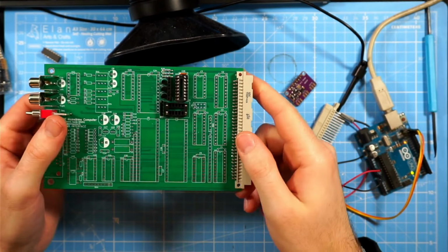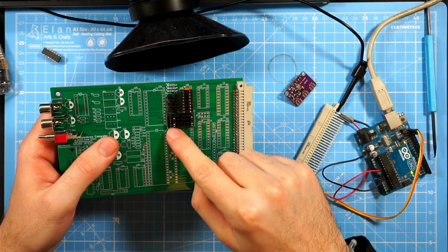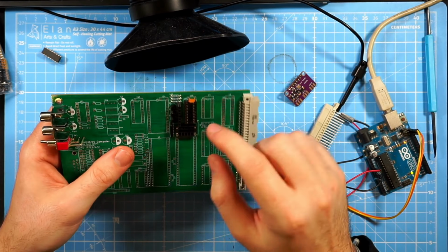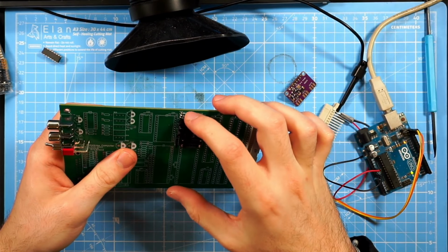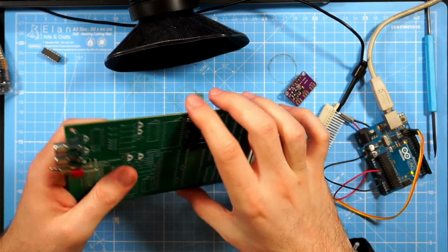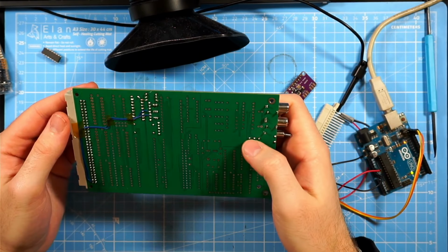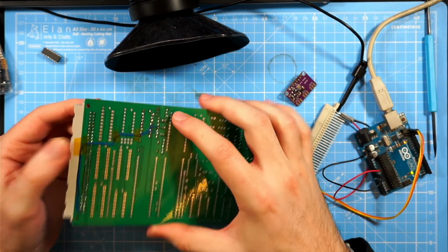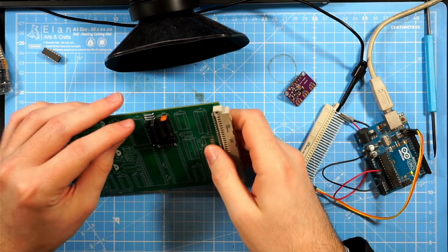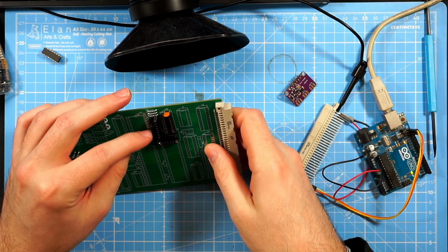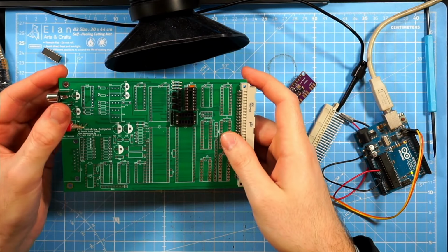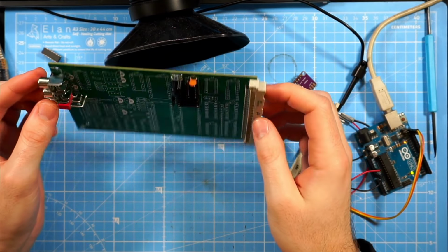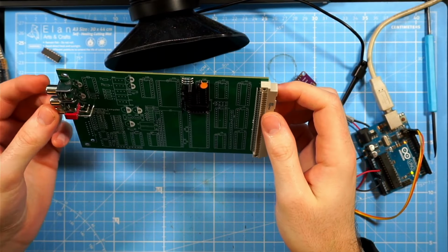Let's see. What I'm about to do is swap this one out with a 1K resistor network and add a 330 ohm resistor to ground for all those collector pins of those transistors, and then see if this makes it work, or if it doesn't and I have to abandon this idea after all.